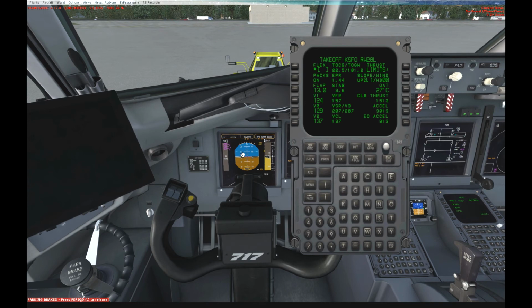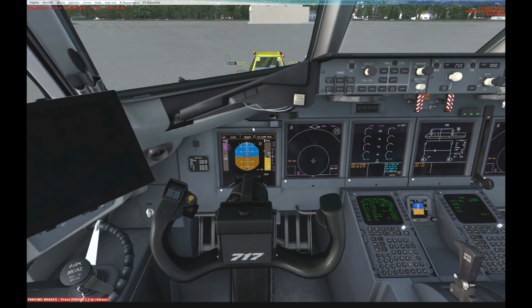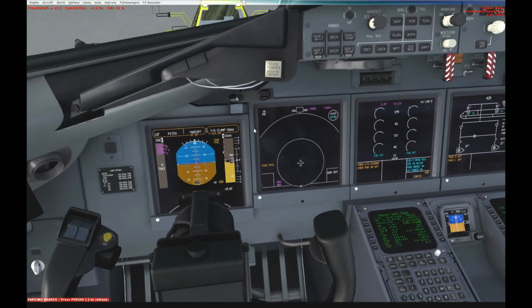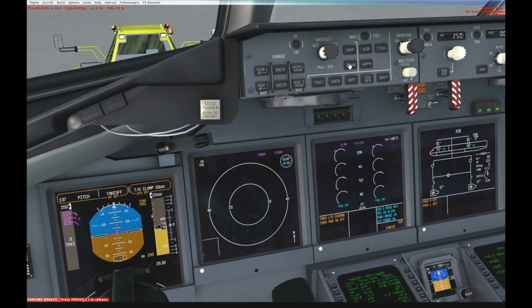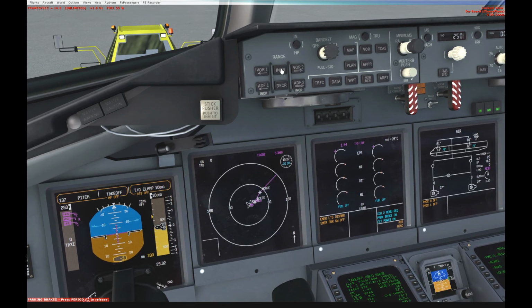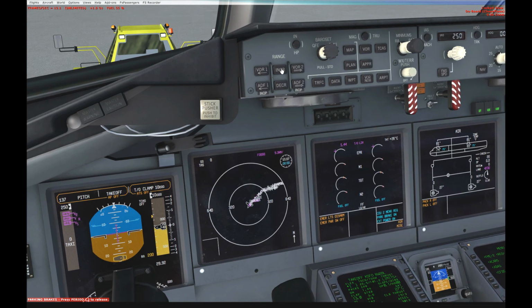Next thing you want to do is confirm your route. So let's go ahead and close that. I haven't done this before, so it's going to take me a while to figure it out. To confirm your route, change this to your plan, like so. If you keep clicking on increment, it goes through the radius of the whole thing. You can go up to 640, you can go down. Now I can tell by looking at this that all my waypoints are in the same area, but a better way to confirm,